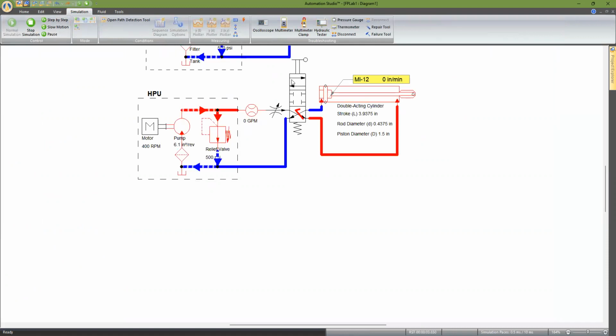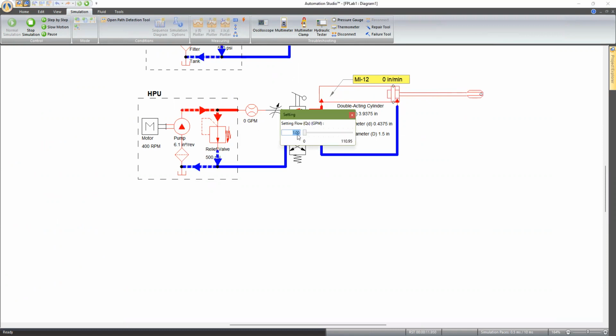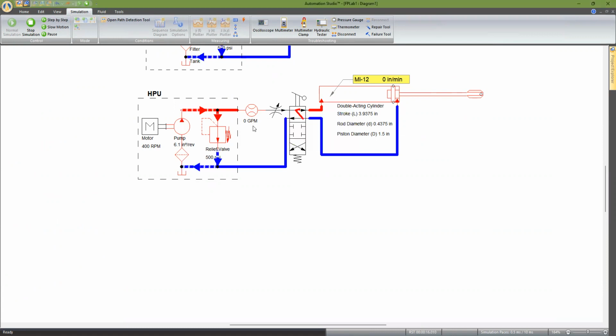and I want to see how much fluid is passing through during extension, I can do that. So I'll click this one. At the same time, I'll watch what is reading. So it's 0.98. Remember, we set 1 GPM here. We are not getting 1 GPM, but very close to that. Okay, so if I retract, again, very close to 1 GPM.